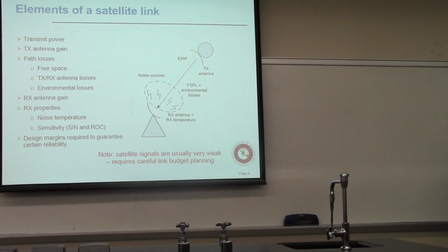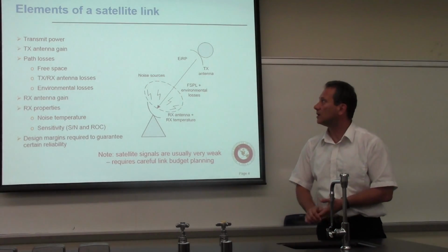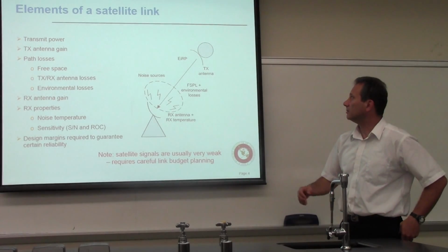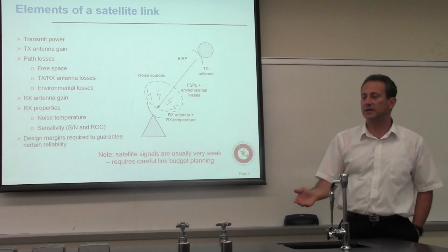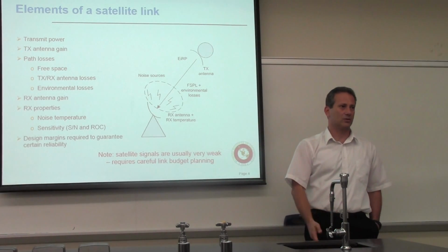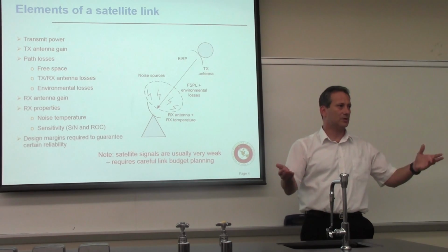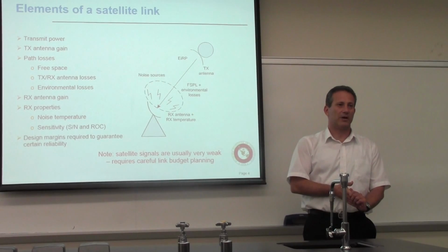So what are the things that you select, that you're kind of juggling here? You are taking into consideration transmit power, and even though you have two links, they're largely asymmetrical. On an earth station, you're connected to a power grid, so you can pretty much send any power within the limits of what is allowed by the spectrum rules, right?